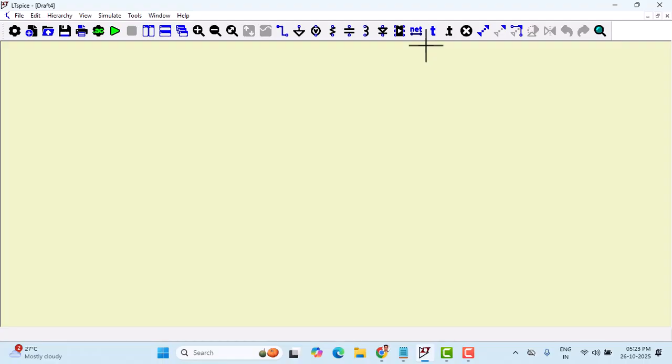First and foremost, here we have a springboard like structure. You can place all the components first before you make any connection. So now for rigging up, for obtaining the voltage current characteristics of a PN junction, what we need first is the diode. Let me bring the diode here. I will click on this.